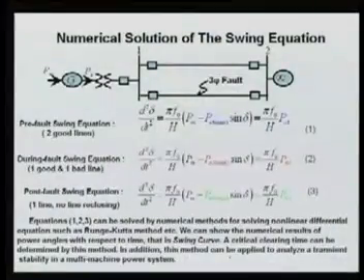Now for the single machine it is very easy to know whether your system is stable or not. We can analyze and calculate your critical clearing time, we can see the stability of the system, and we can only know the relative stability. We want to get the delta variation. It is not a time domain simulation at all, it is only giving information about the stability of the system, meaning your system is stable or it is not stable.